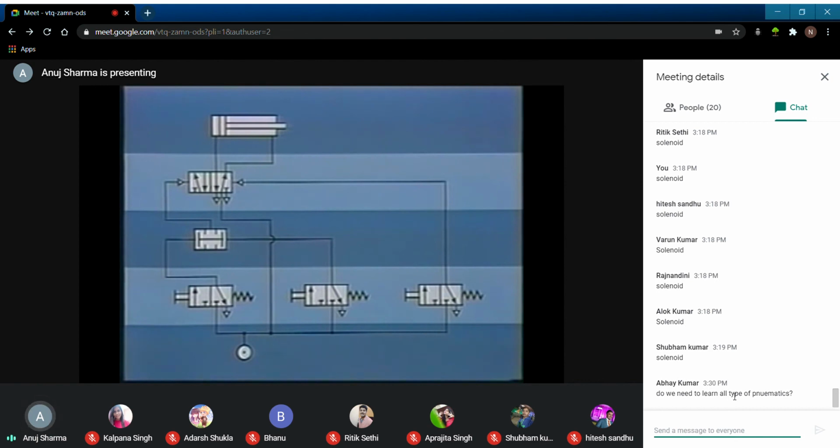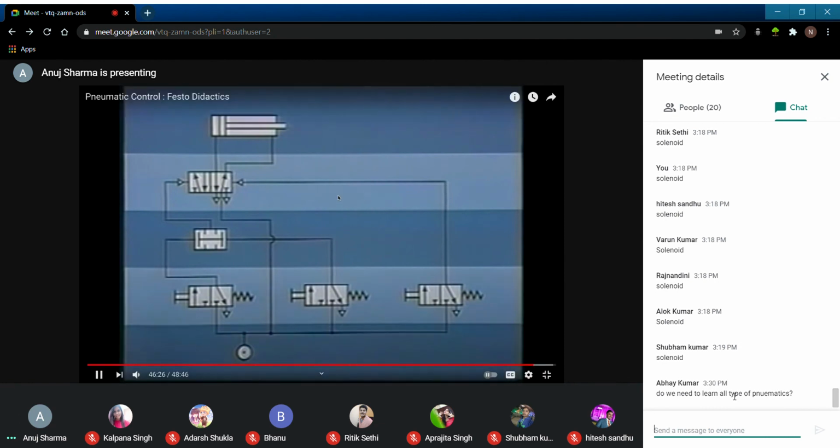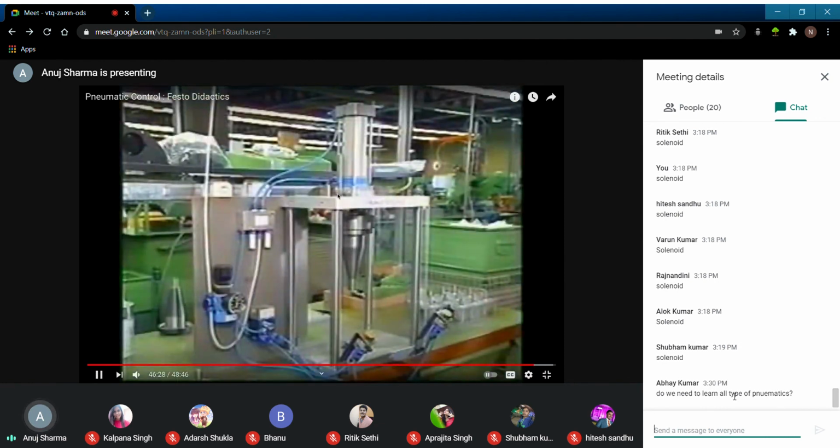Let's look again at the 5 principal levels of a pneumatic circuit. Energy supply, signal elements, processing elements, control elements, actuators. Each of these levels can be identified in the actual machine circuit.